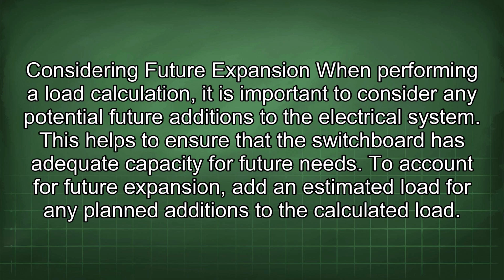Considering future expansion. When performing a load calculation, it is important to consider any potential future additions to the electrical system. This helps to ensure that the switchboard has adequate capacity for future needs. To account for future expansion, add an estimated load for any planned additions to the calculated load.